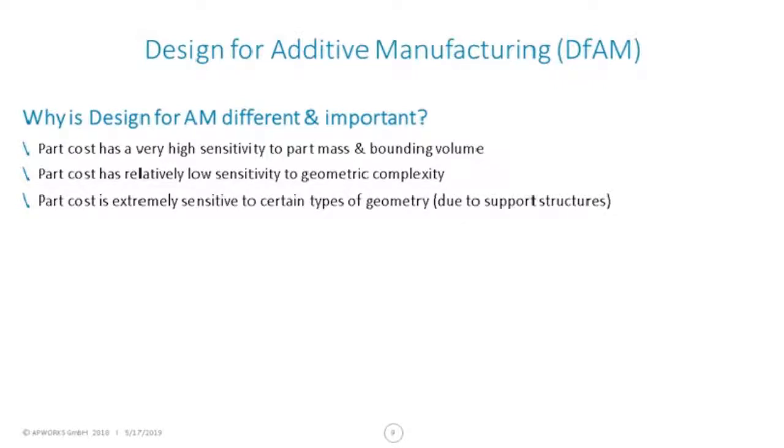Traditionally, we would think that's easy. You know, it's a block, we just machine it, done. And by additive manufacturing, that can be extremely difficult to produce because of thermal stresses in the process, and because of the support structures needed. So if you take a traditional design and you simply go to someone and say, please produce this by additive manufacturing, you will almost always be disappointed because it will almost always come out more expensive and you'll wonder why anyone is using it.